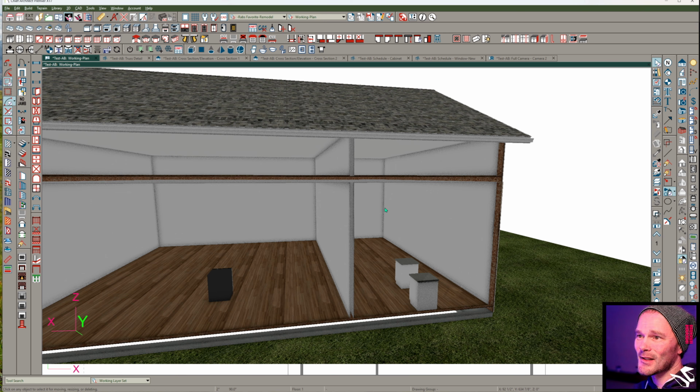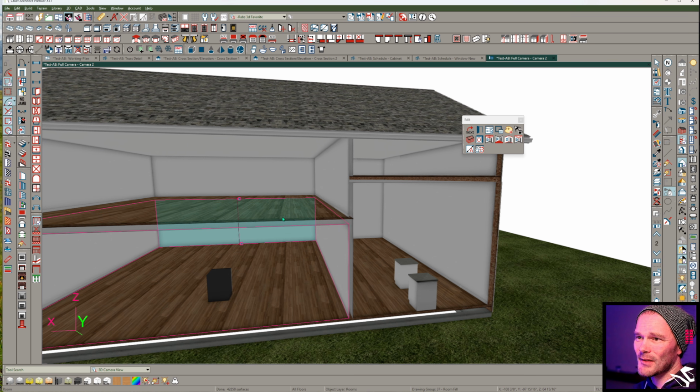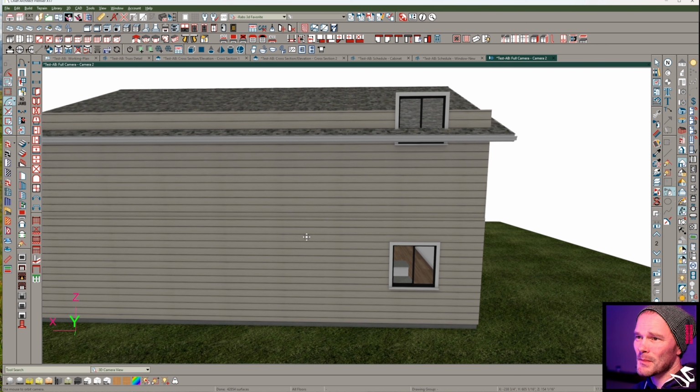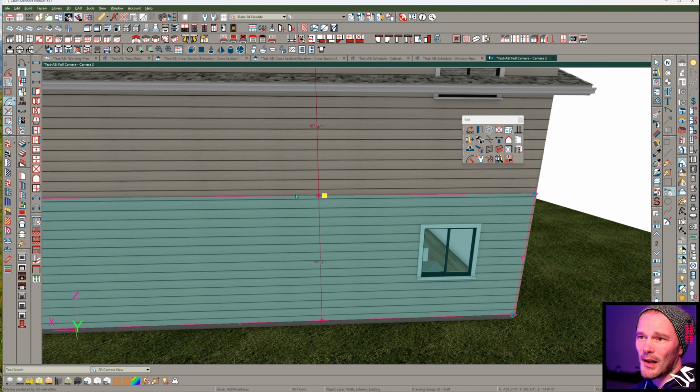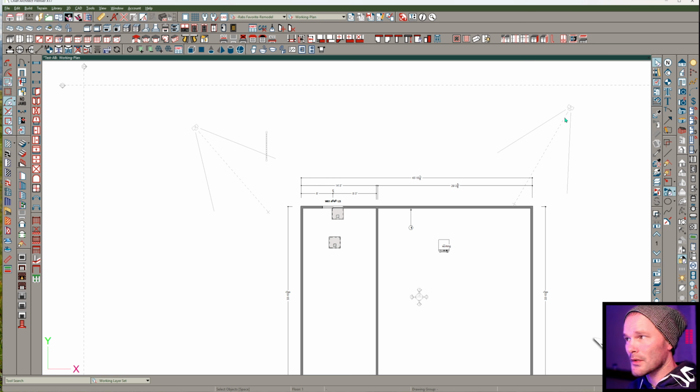Okay, so now if I change these relative heights, a lot of times things will get fixed if you add a break at that intersection. Little goofy transition things, wall intersections, all kinds of things can be fixed if you add a little break in there. This plan's getting real rough, so let me start a fresh one.